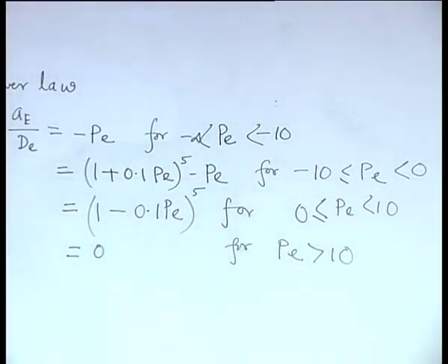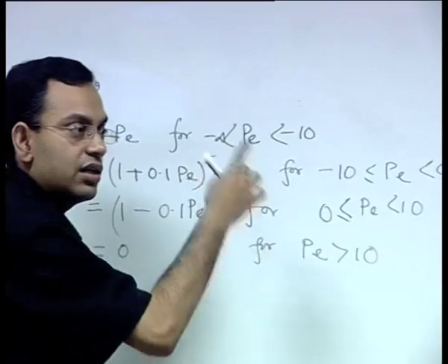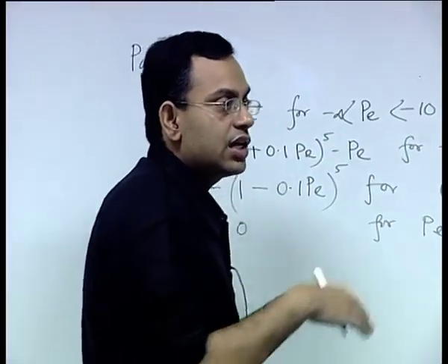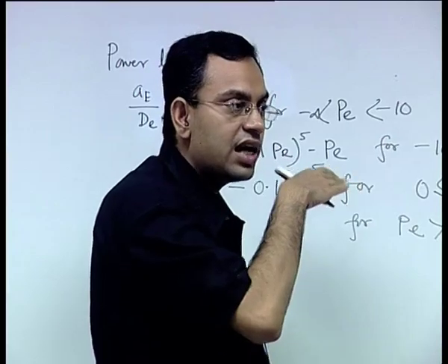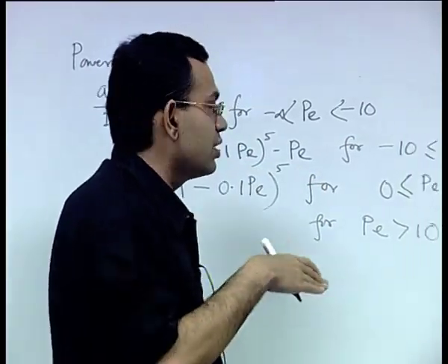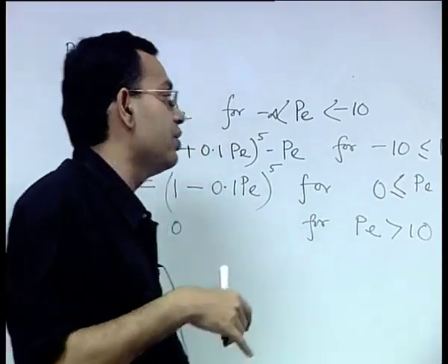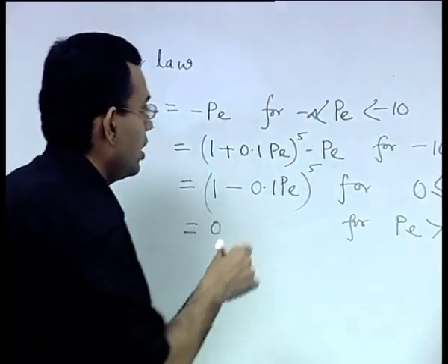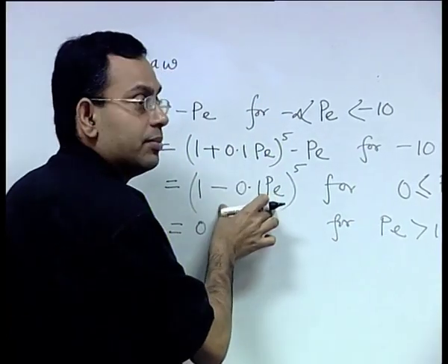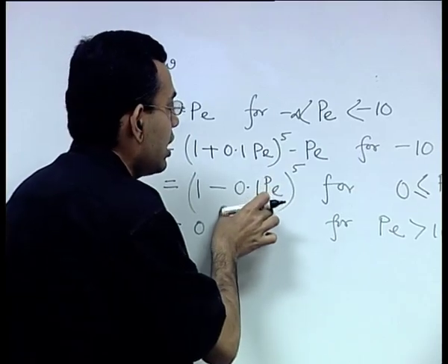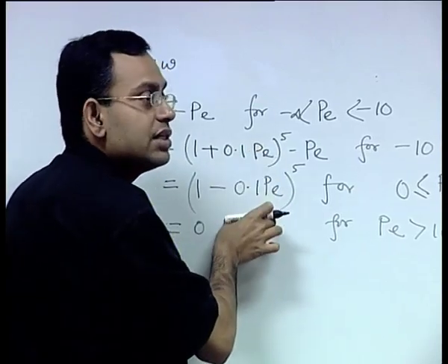So instead of considering Peclet number equal to 2 as a switching parameter, Peclet number equal to 10 is considered as the switching parameter. The exponential behavior is such that it dies down to 0 for the corresponding argument tending to 10 in terms of magnitude. So now where do these formulae come from? These are essentially curve fitting of the exponential behavior.